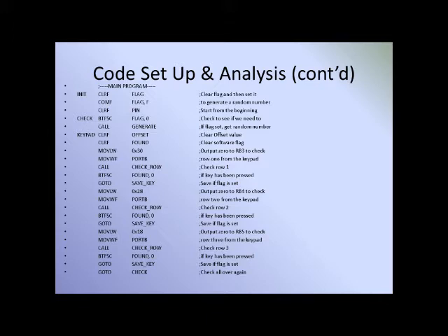This is why the program begins by checking the rows by loading different literal values into port B bits in order to isolate each row. For instance, we load 30 hex to isolate row 1, 28 hex to isolate row 2, 18 hex to isolate row 3. After these values were loaded into port B, respectively, the check row subroutine was called.